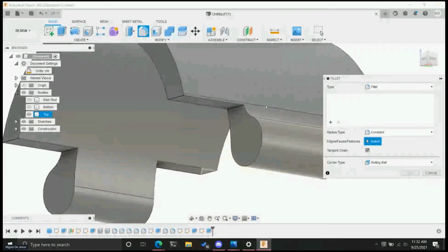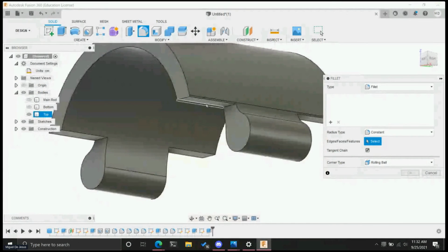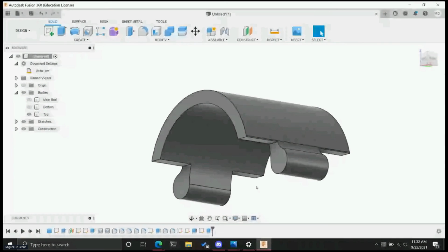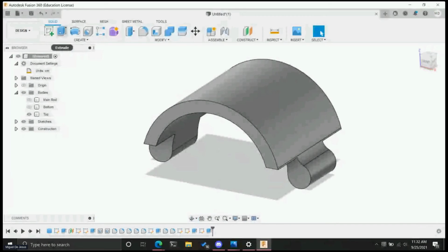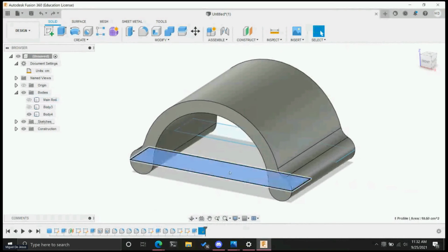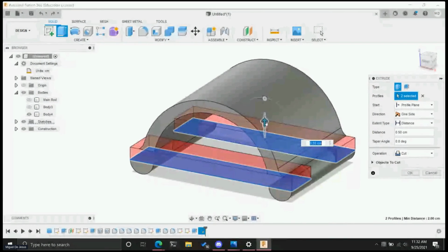So I have a problem here, and it's basically that tiny little piece, and that's because we didn't actually extrude it correctly. So we need to actually go a little higher with the extrusion. See if I can go back, fix that issue. I go up actually 0.8.